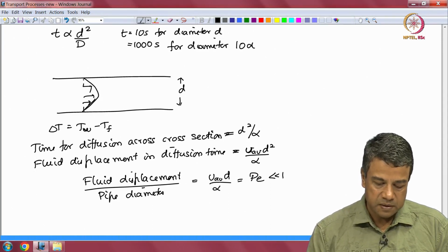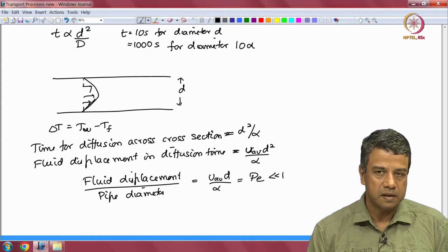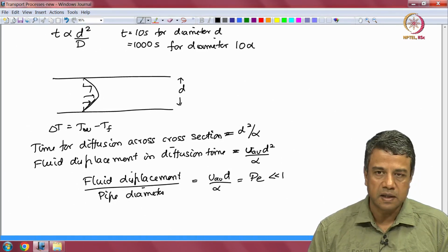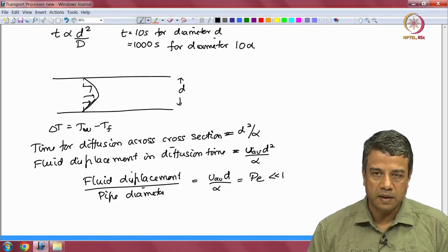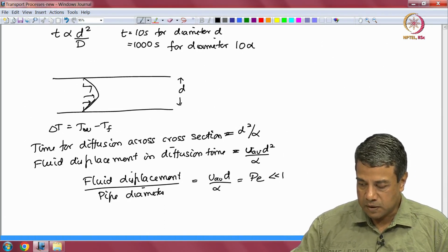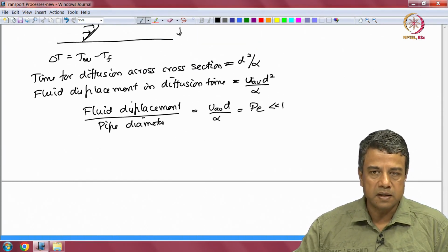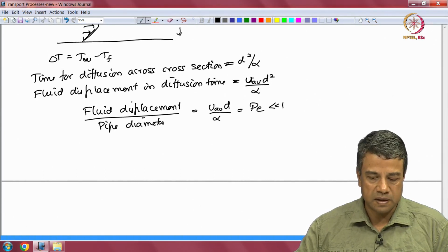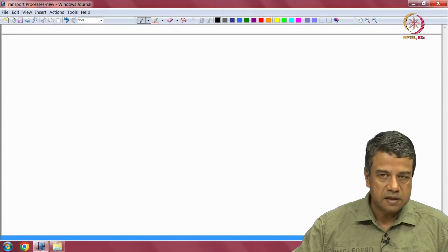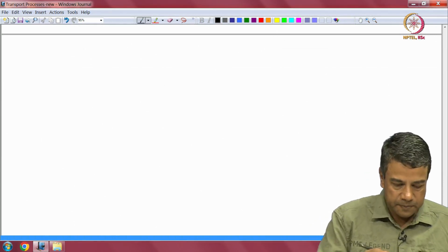The transport in pipes and channels is almost always operated in the limit of high Peclet number. The reason is that in the low Peclet number limit, since convection is not important and diffusion is dominant, the temperature equalizes across the entire cross section before the fluid has moved very far. So that is for low Peclet number. The Nusselt number or the Sherwood number is just a constant.